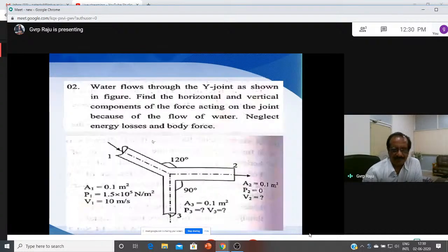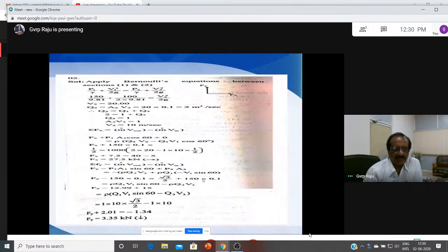And suppose if you see here, because the pressure is 0, so there is no other P2 A2 here. So P1 A1 cos 60 plus 0, that is the pressure here, which is equal to rho into Q2 V2 minus Q1 V1 cos 60. So you can also resolve this V1 in the x direction here. If Q is not constant, you can take inside. So the momentum equation, sum of the forces here we have taken, and Fx is the force by the fluid on the bend. If you remember the discussion on momentum equation.